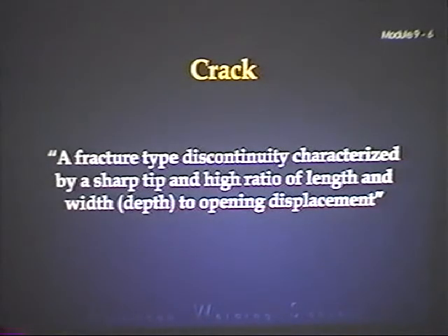And that can cause that metal structure to change to a martensite structure, which results in your cracks. It says, as explained in Chapter 11, when the carbon content in steel is high enough, heating it to above the critical temperature and quenching it results in the formation of martensite. Low carbon martensite can even form in low carbon steel if the quench is drastic enough. With the addition of alloying elements, martensite will form at a lower carbon content and at a slower rate.